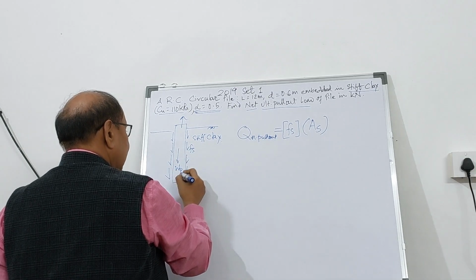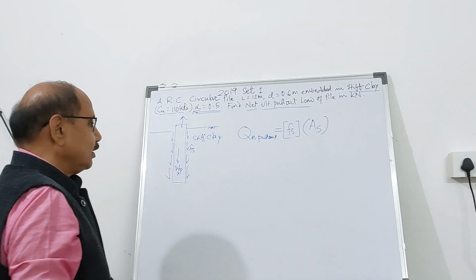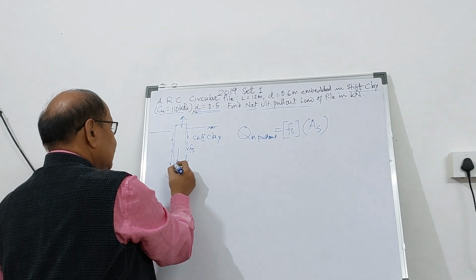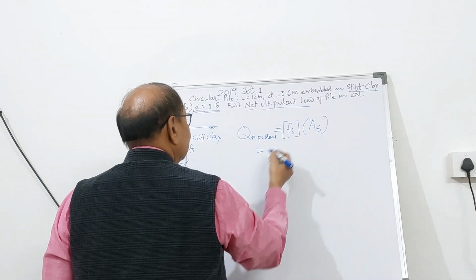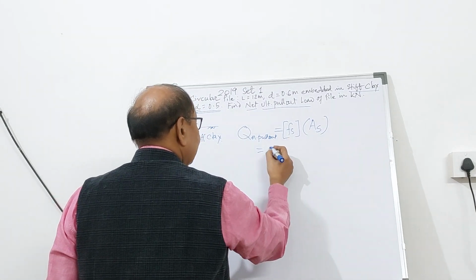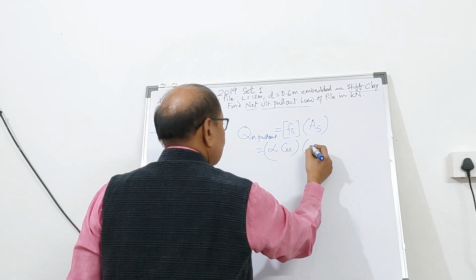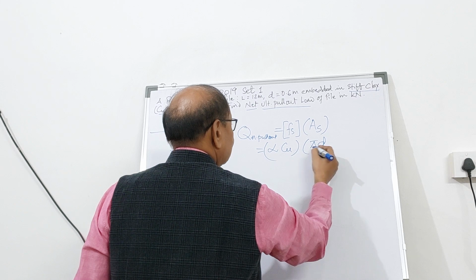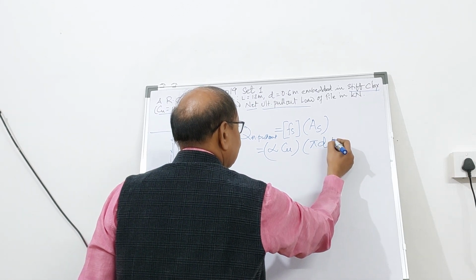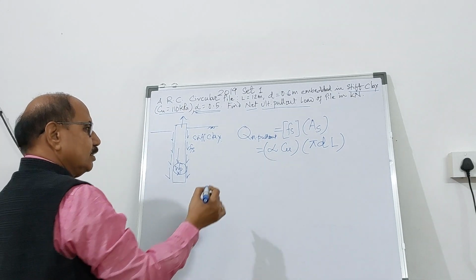The weight of the pile will not be considered in net. If it is total, then consider this. So as you know that in a stiff clay, Fs will be alpha times Cu, and this will be, it is a circular pile, so perimeter will be pi d and multiplied by length. That becomes the shaft area.